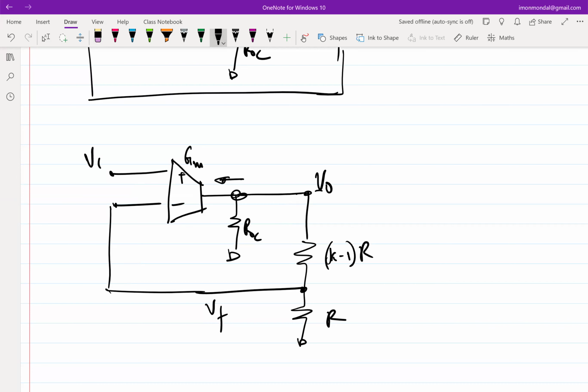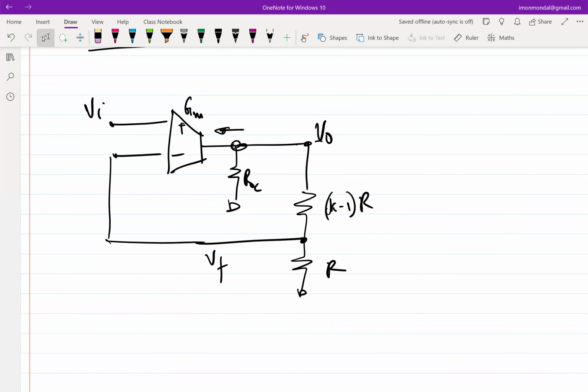Okay. So this becomes the loop. So what is the loop gain? How do I figure out what is the loop gain? So a couple of things to do. Again, the same algorithm. One is obviously you have to short the input. Without shorting, you will not get loop gain. So I short the input, all in the incremental domain. Then I break the loop. I would like to break the loop in a place where there is no effect of loading, right? So can I break the loop here?